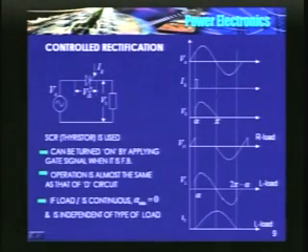Okay. So far we discussed uncontrolled rectification, full wave as well as half wave. Now we will go in for controlled rectification. I need to use a 3 element device. So we have already discussed the SCR: anode, cathode and the gate. We can turn on the SCR when it is forward biased by applying a positive gate signal with respect to the cathode, that we have already studied.